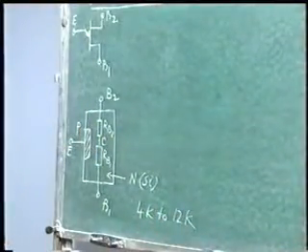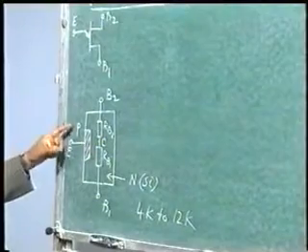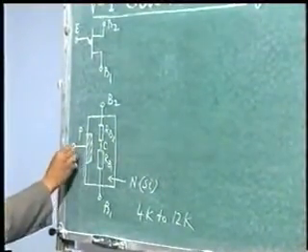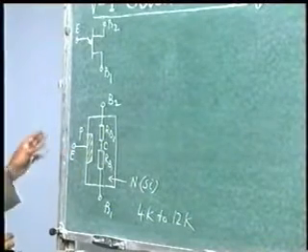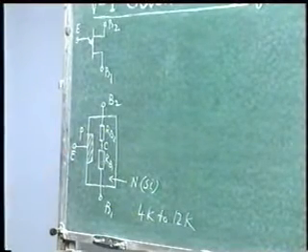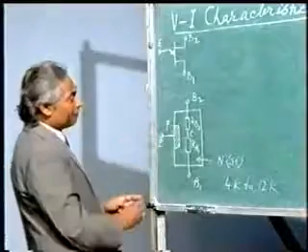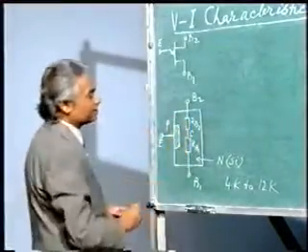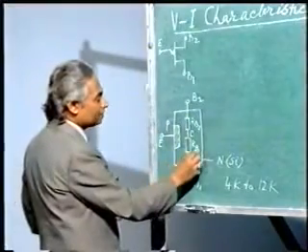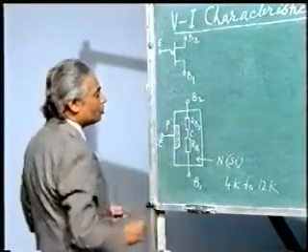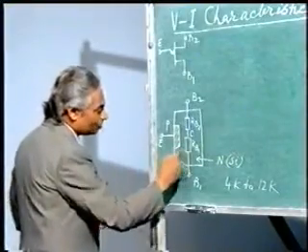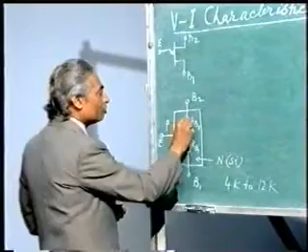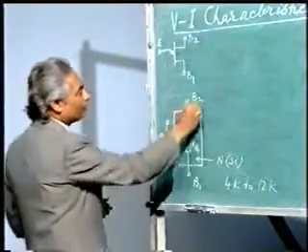When a p type material is diffused in it, a junction is formed, and from that junction another terminal, which is emitter, is taken out. So the geometry of the device is such that it is divided into two zones of resistances, and from zone 1 we have one base terminal, we call it base 1. From zone 2 we have another base terminal, we call it base 2.